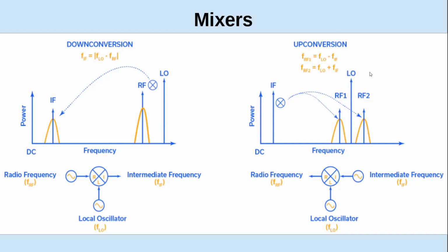Okay, so we're going to take the sum and the difference of the local oscillator and the IF input frequency and generate these two sidebands on either side of the local oscillator. So in this effect, from a transmitter standpoint, this would be your carrier if you don't do anything else to it, plus the two sidebands. So that would be an AM signal.